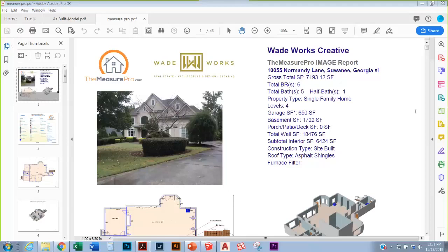Matterport is somewhere between a 16th to an eighth of an inch of accuracy. I'm only telling you guys solutions that get us within an eighth of an inch, which is the acceptable tolerance for really what we need to be doing for as-built docs.